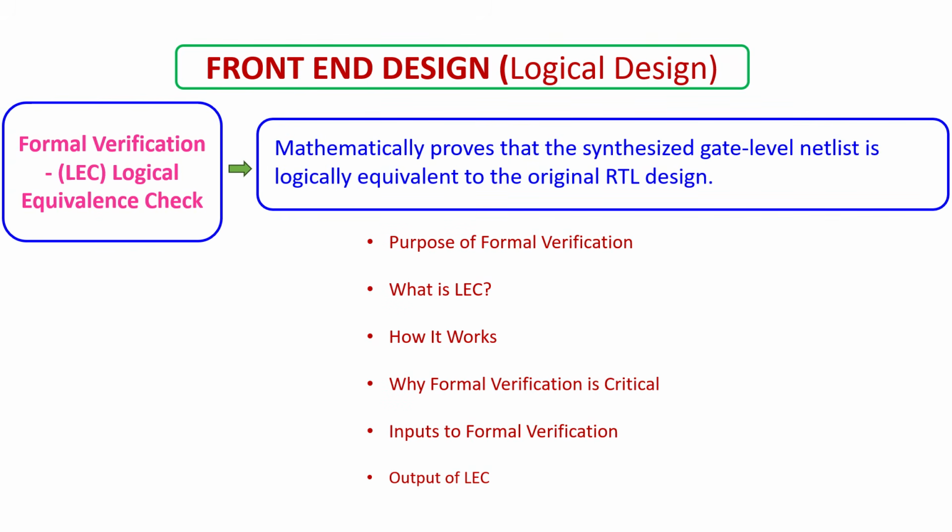The next stage is the formal verification stage, LEC, logic equivalence check. This stage proves that RTL is equal to the netlist. After synthesis, we must ensure nothing changed logically, and this stage does that.